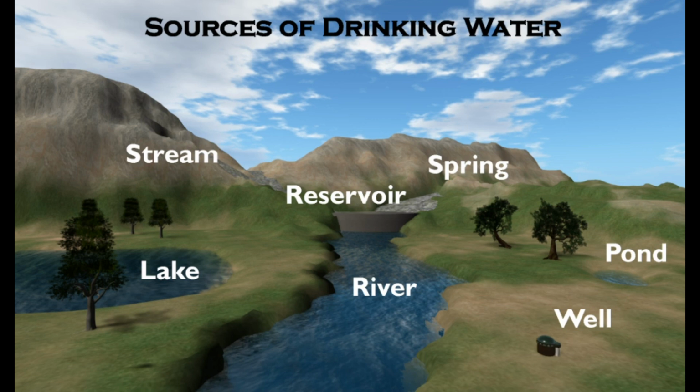Usually in surface water bodies, the dissolved mineral particles will remain unchanged, while the organic impurities are degraded by chemical and microbial action. In slow flowing or impounded surface water, sedimentation of the suspended solids occurs naturally. Due to lack of nutrients, microorganisms will die off. Although clear water from rivers and lakes requires no treatment, taking into account the risk of incidental contamination, it is better to practice chlorination.